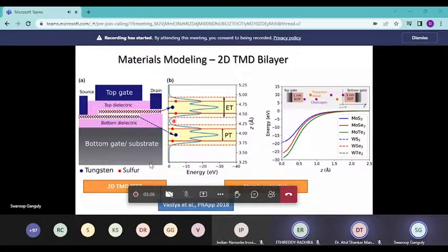Atomistic potentials corresponding to the chalcogenide atom, right? That actually doesn't die at the atom itself. It sticks out, and then effectively the separation between the layers is reduced. And that changes the capacitance, that changes the threshold voltage if you are designing a device with a bilayer like this. So this was some interesting insight we could get from atomistic materials modeling.